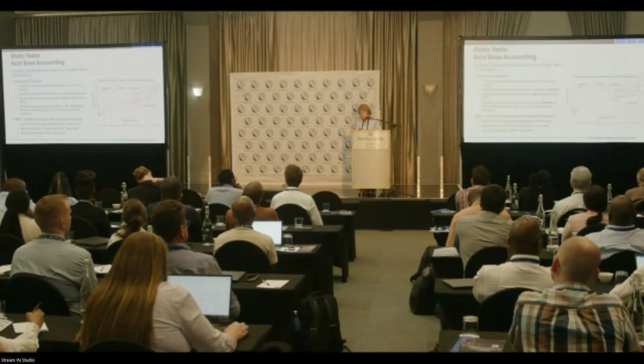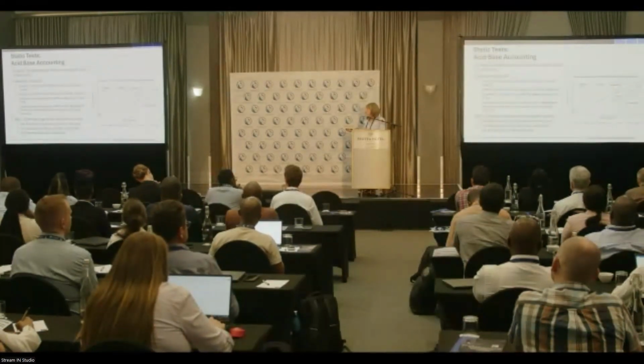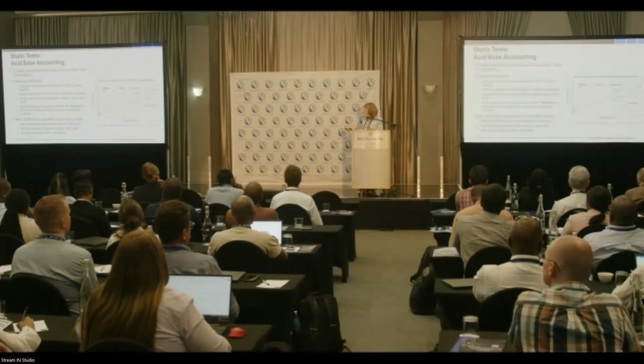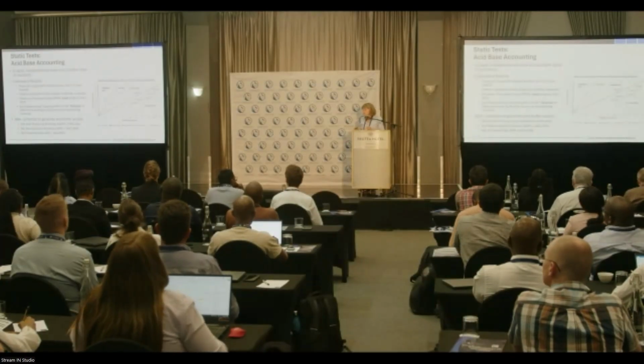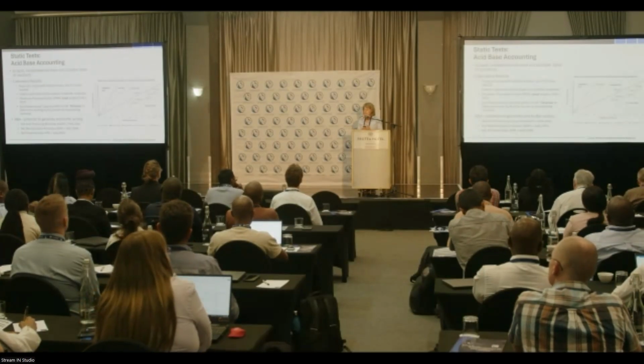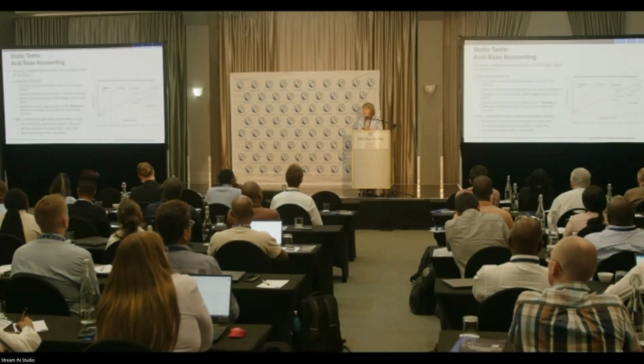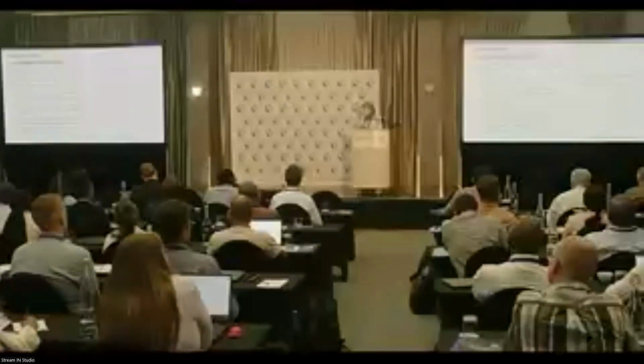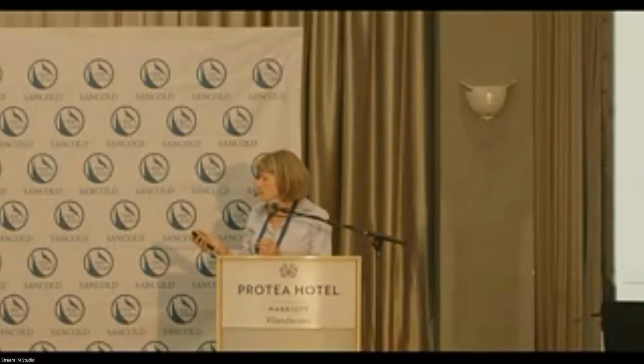And there are plenty of graphs out there. I've just put in one example, but generally you would plot your net acid producing potential, which is your MPA minus your ANC, and you'd plot your net potential ratio as the ANC over the MPA.